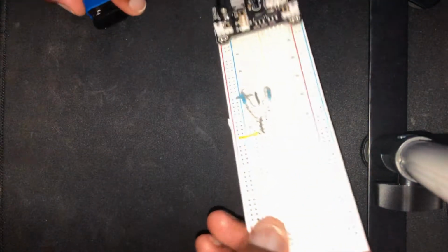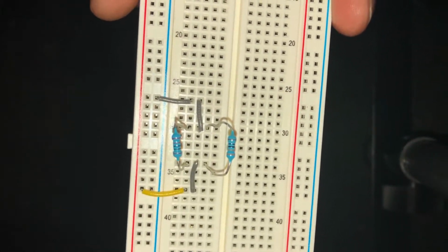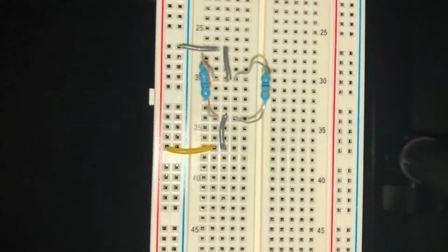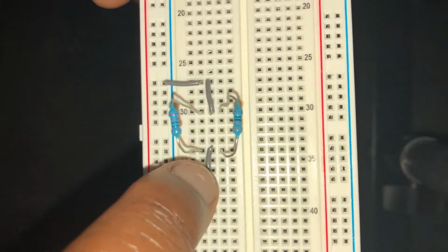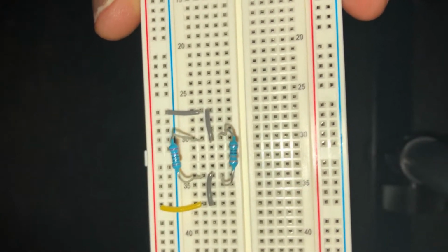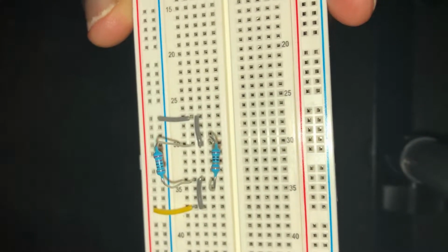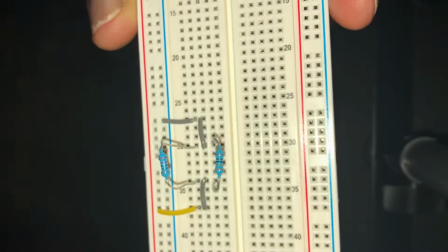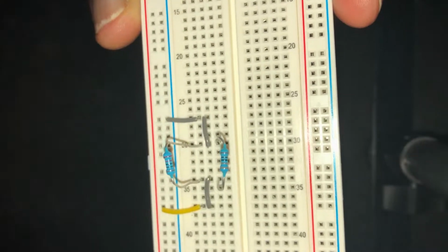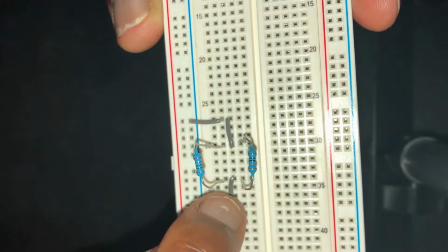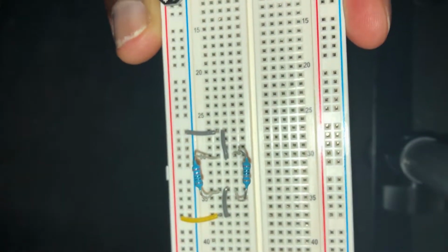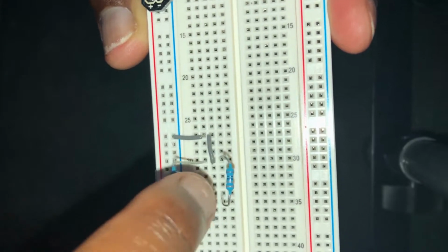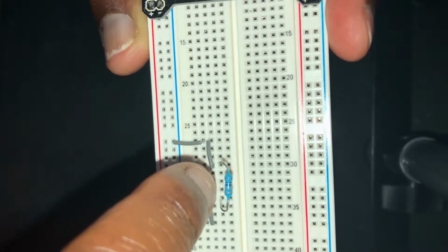So the next circuit basically has the 220 ohm resistor and 330 ohm resistor in parallel with each other. So I've got power coming in on this side, and I've used 2 extra small solderless wires to recreate the parallel circuit more like what we drew earlier on. So the current splits off at the junction there. Some current goes into there, some of it goes into there, depending on their resistances. And the current then comes back together at that junction and then goes to ground.